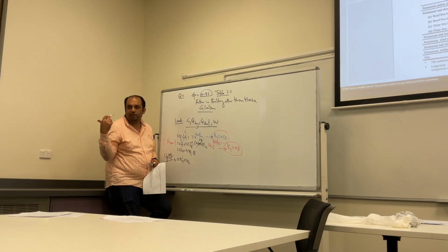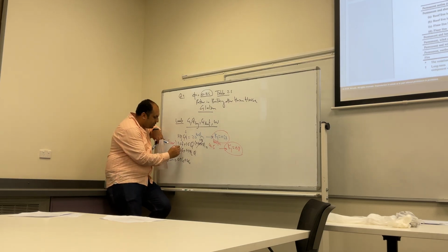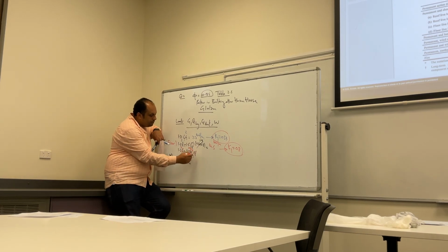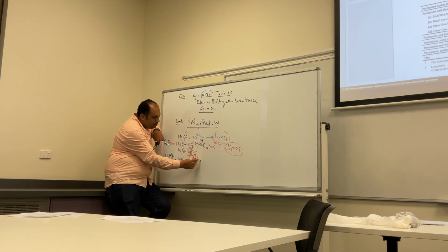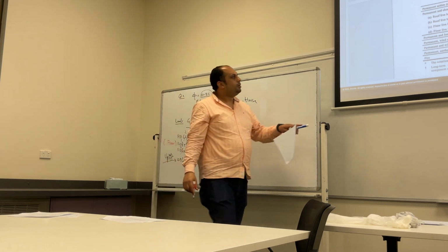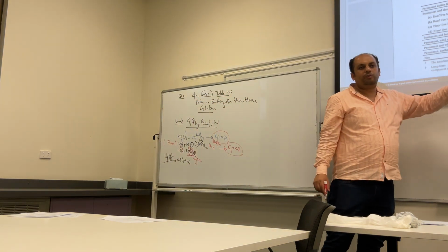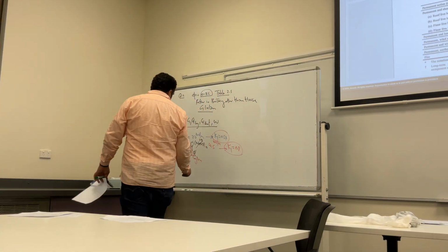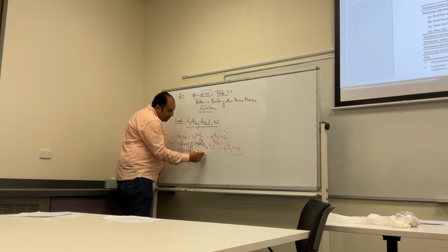Because the first one he clearly mentioned it is for a roof, but this one he didn't. So this one is 2. How much is psi L in this case? 0.4. How much is Q? Q here is the long term load. Can you see? Psi L means long term. Yeah, long term. So we only consider what? Long term. 0.6 or 0.8? 0.6. So this one is 0.6. Can you find this value?